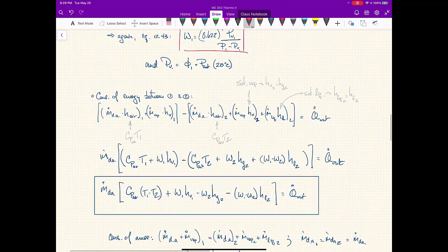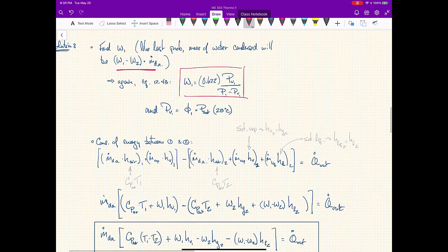But specifically, I look at what I know for a flow such as the one going through this dehumidifier. I don't know a whole lot of things. I know the state that I've measured, which is given to us: the relative humidity both at the inlet and at the outlet. I know the temperature both at the inlet and the outlet. That's T1 and T3, and Phi1 and Phi3. I also know, based on the data given, that the total pressure of the mixture remains constant throughout this entire process at 1 bar. So this is all I know in terms of raw data.